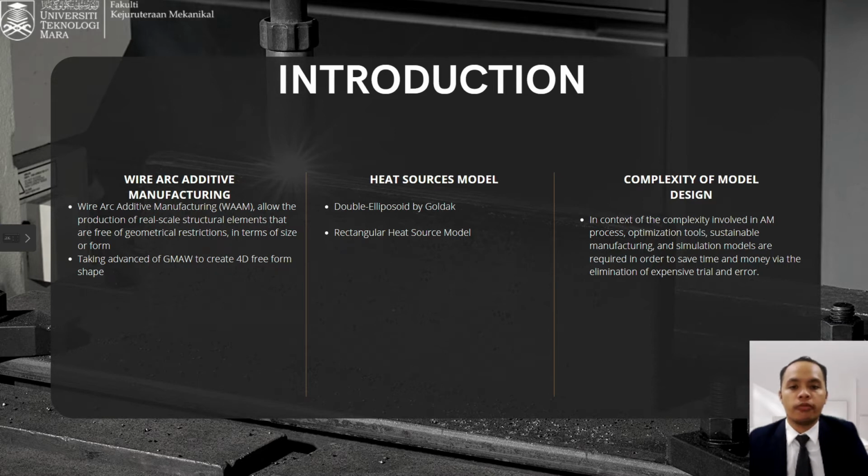Next, the most significant boundary condition in numerical analysis is the heat source model. Therefore, the appropriate heat source model must be chosen according to the welding process. Hence, the heat source models that will be applied in this FE simulation are the double ellipsoid heat source model by Goldak and the rectangular heat source.